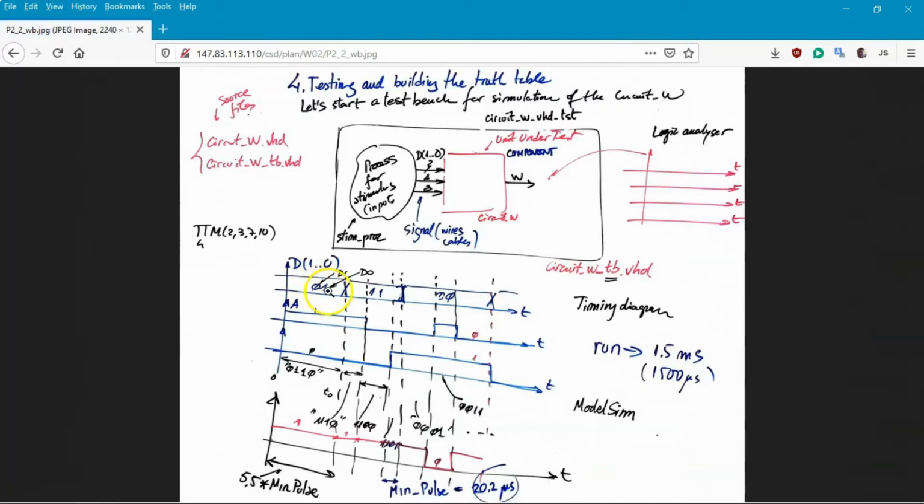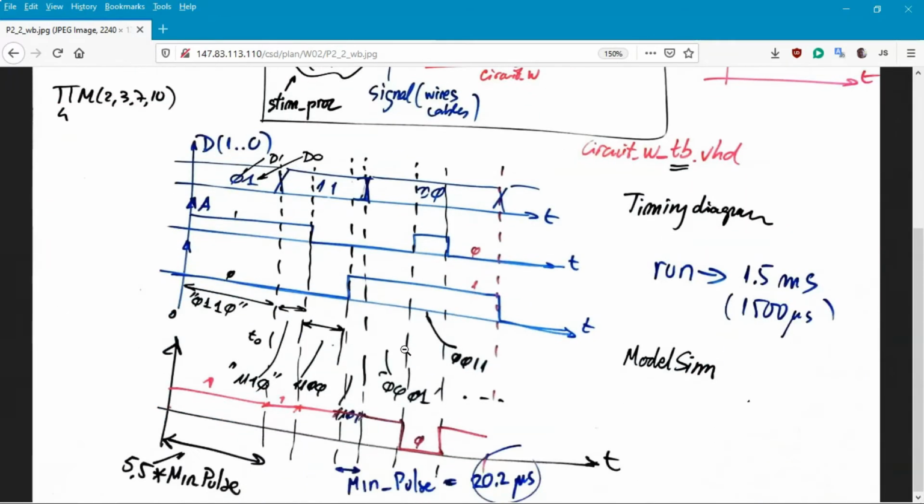We would like to verify very well that the circuit matches this table, but we have to do that, you know, by applying inputs in time. Okay, applying the D10 and applying the A and applying the B, giving them different values. Now, because this is the very beginning, it doesn't matter if you apply all the values, just some of them to see that it's going to work.